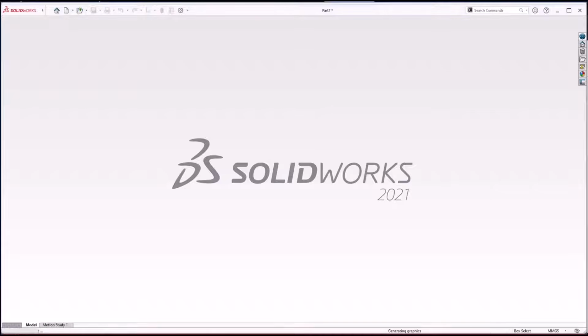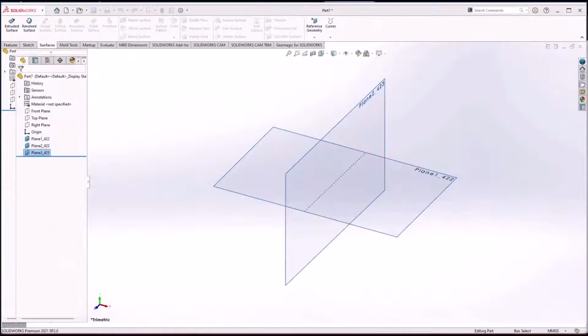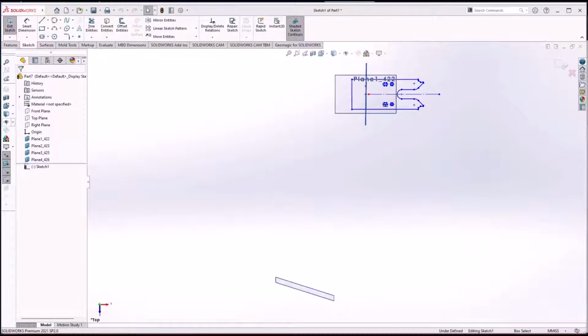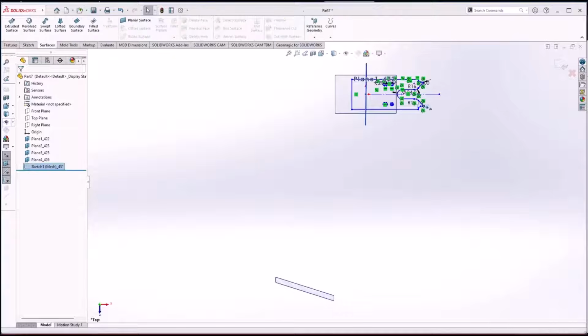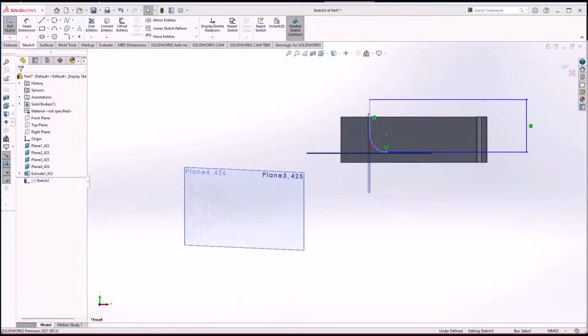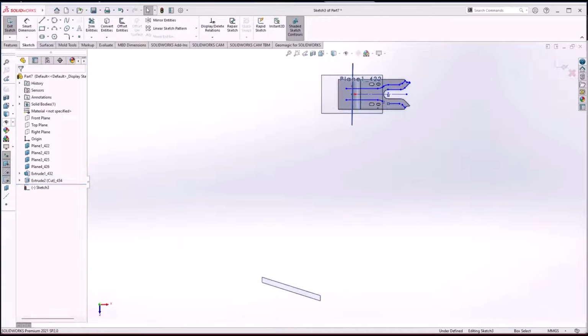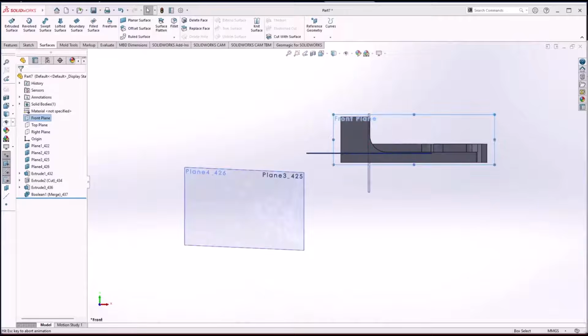And you'll see it pop up here on screen. And it kind of looks like an animation, like you're watching a movie of something happening here. And that's because it kind of is. In the background, LiveTransfer is using the software itself, SOLIDWORKS, to send over and transfer everything one for one. So it sends over the individual sketches and all their entities in the same spots with the dimensions and all of that. And it comes across, and then it closes out that sketch.